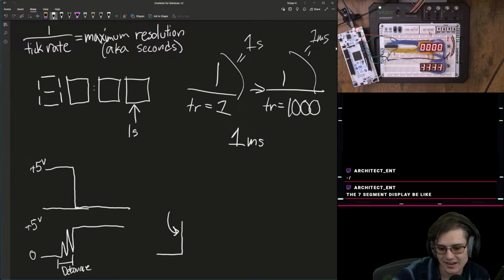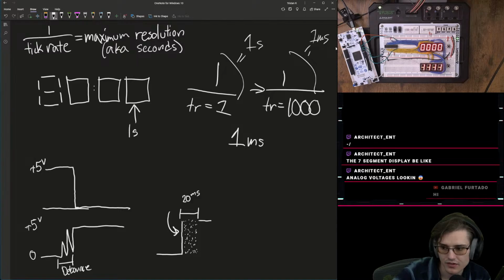The instant that happens, do a sleep for like 20 milliseconds, let's say, where you just ignore all the data, all the sampling that could happen. Your processor does not check back to see what the value of your button is until afterwards, and it looks stable.